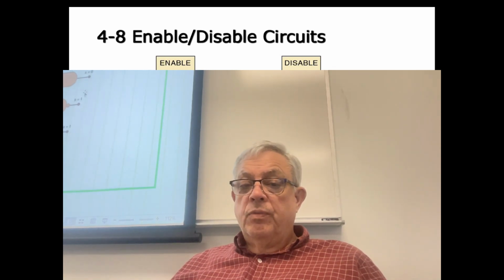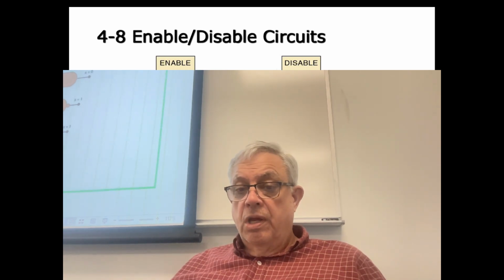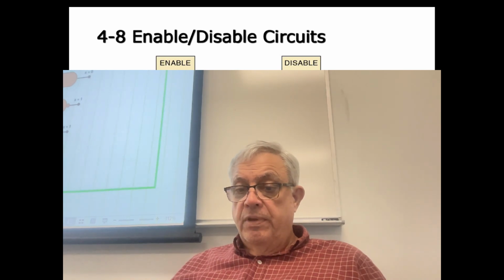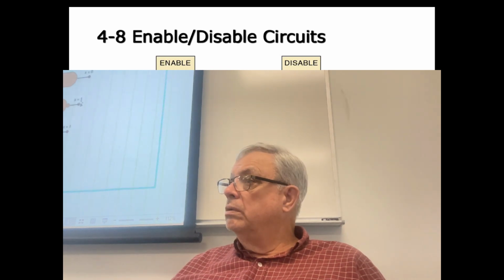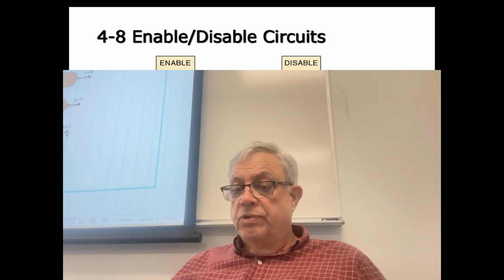I can do the same thing with the disable circuits. Same process. If I make B a 0, I've just shut off the output. If I make B a 0 here, the output goes to a 1. Doesn't matter what's at A, the output's at 1. The OR gate, if B's a 1, then the output's at 1.